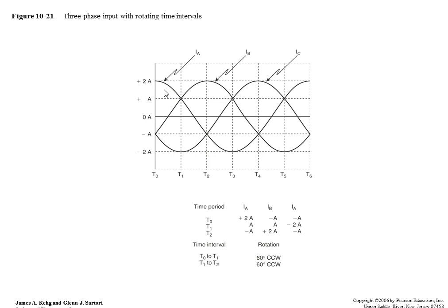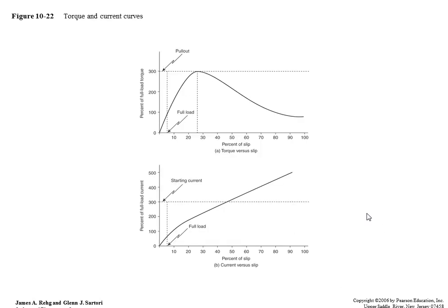This is how I'm going to move clockwise or counterclockwise. If I'm wired T1, T2, T3, I'm going to go clockwise. If I'm wired T2, T1, T3, then I'm going to go counterclockwise. My motor doesn't care which way it's rotating. It'll depend on how you wire it. The water would care. The beer would care. The malt would care. The paint would care if the pump went the wrong way, right? So don't be rotating your motors the wrong way.